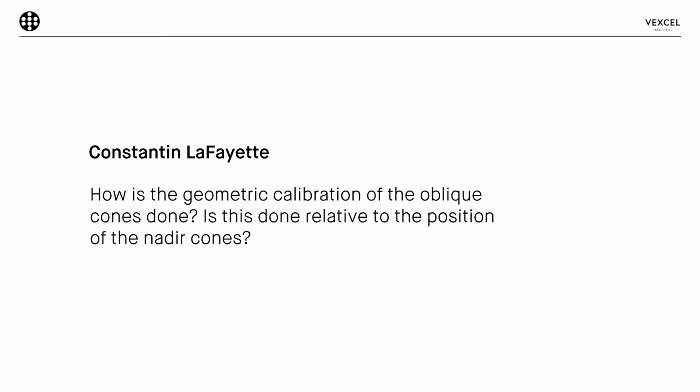In addition to that, we optionally provide a tool in UltraMap AT, in the bundle adjustment section, where these parameters can be estimated by the software based on the project data. So the eccentricities can be estimated based on the project data and are applied to all the processing in this project. Thank you.